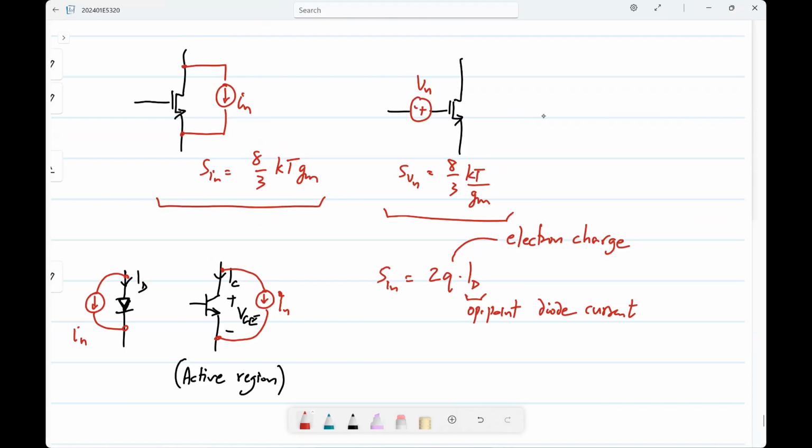The noise from different physical sources is uncorrelated, but you should preserve the polarity through the calculation, because depending on the circuit analysis technique you use, if you flip the polarity in the middle, it won't work. Wherever ion appears, you use consistent polarity for it. You don't randomly flip signs, but you can use the source itself in any direction that you want.